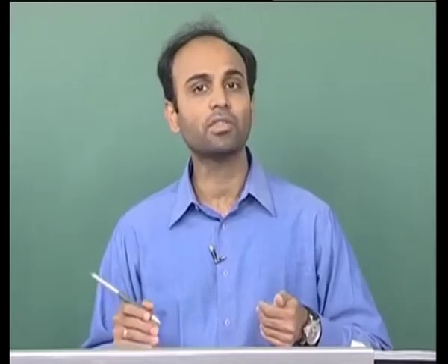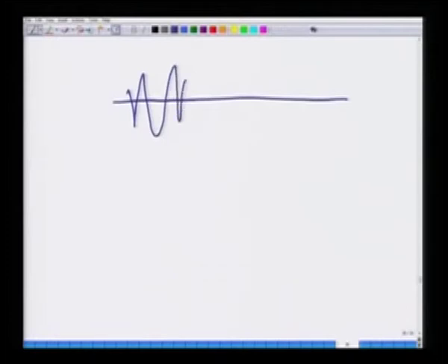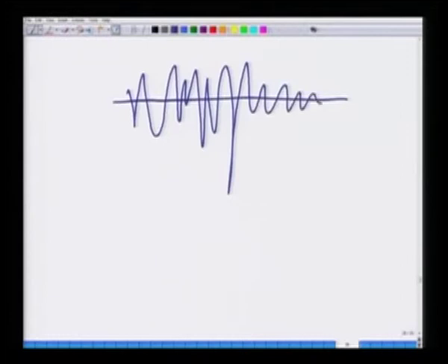You receive a range of signal powers at the receiver depending on the random nature of the multipath components in the channel. So, at the receiver, it looks as if the signal is going through a set of various strengths. For instance, in one case you might receive a signal of very poor power, 0 power. In another case you might receive a signal of very high power. So, if you plot the signal quality versus time, it will look like some curve where the signal power, for instance,